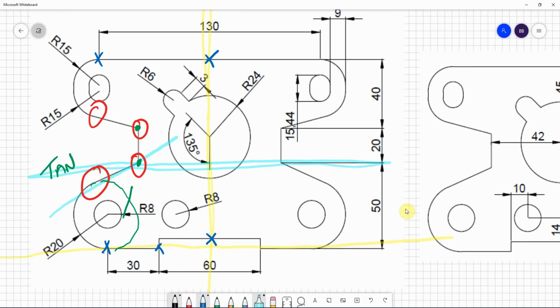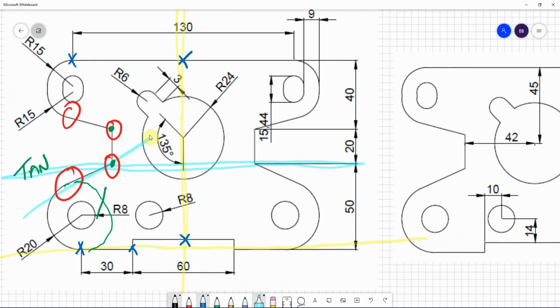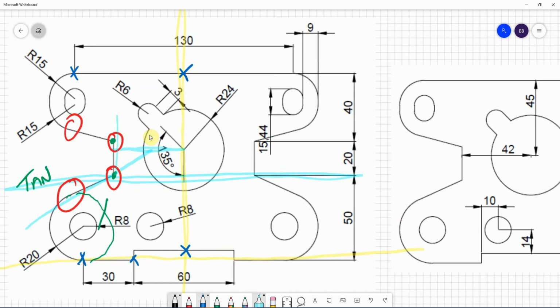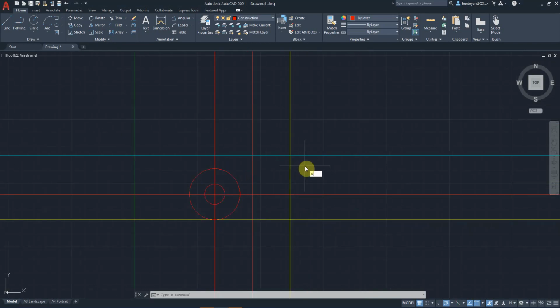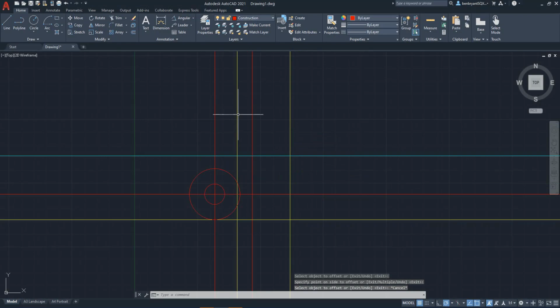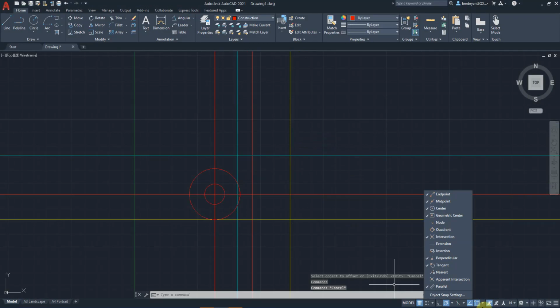Next thing we need to do is work from our center point. So this yellow line here, we need to work from the yellow line out to this line here. I know that on the drawing it's designated as 42. So the last thing I need to do, I'm going to keep this line also blue, is offset 42 from my center point. I'm also going to color that the same bluey color like I did before, just so I know that that is the point of my green splodge on my drawing.